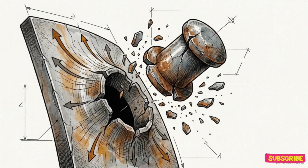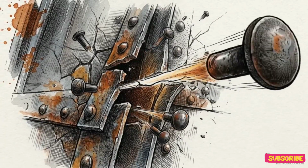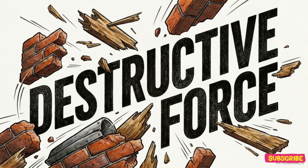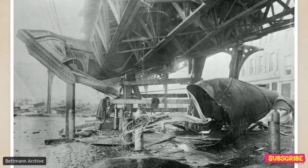Rupture became inevitable. A marginally engineered closed system, lacking the safety margins to absorb thermal expansion and gas generation, simply could not hold. At 12:40 p.m., the combined hydrostatic and pneumatic loads finally surpassed the critical shear strength of the metal. The iron rivets sheared off with sounds like machine gun fire, and the tank's structural seams completely unzipped. The immediate displacement of that dense fluid generated an initial kinetic wave, moving at 35 miles per hour, acting as a massive wall of blunt force. The momentum of this dense liquid was high enough to demolish buildings and flatten an adjacent elevated railway structure instantly.